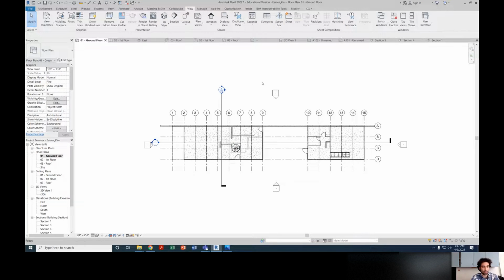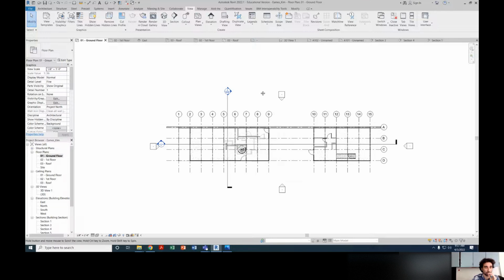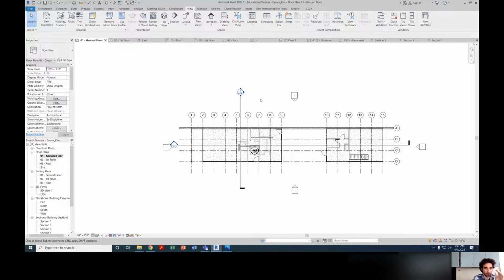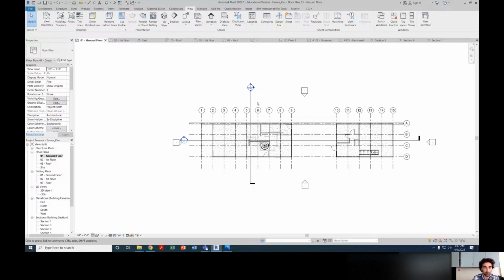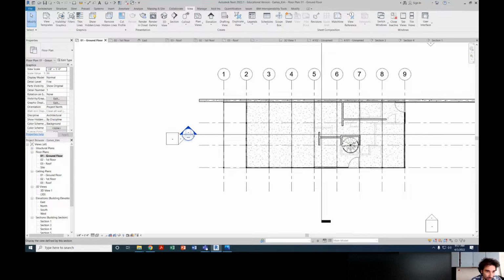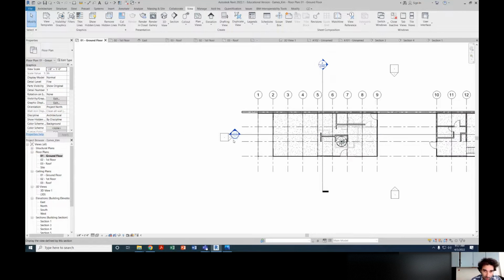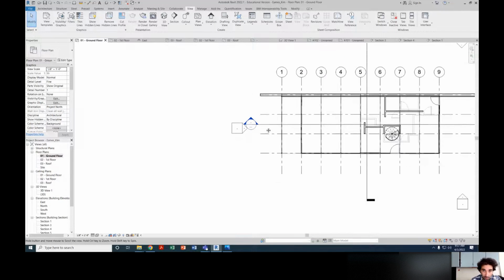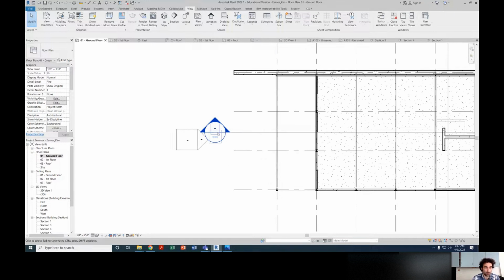So all of these things that Revit is adding are pieces of really good information that we do want to be adding. And if Revit wasn't doing this, we would be doing this manually after the fact. So when I put this on the sheet, this is going to probably say 3A102, which is what we want because it will be the third drawing on that sheet.